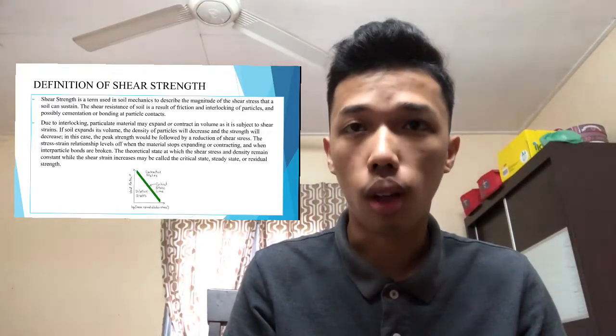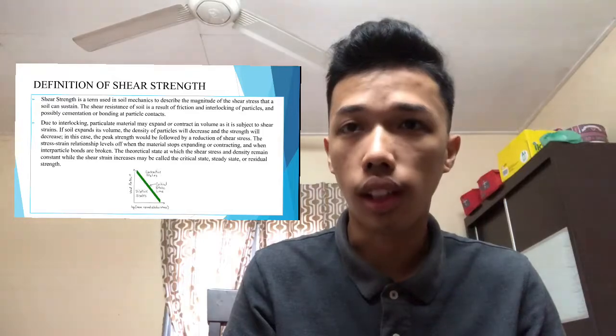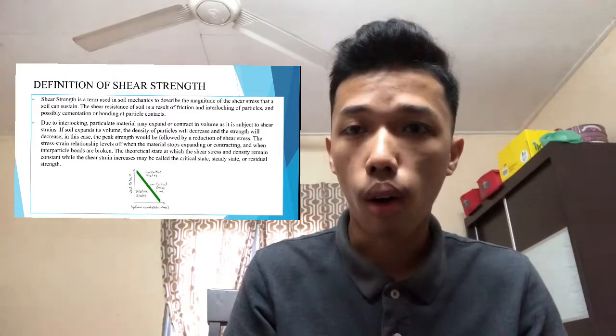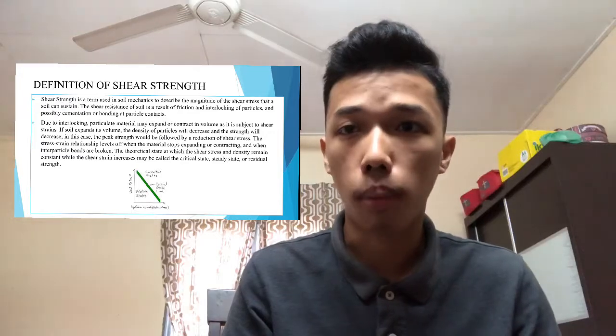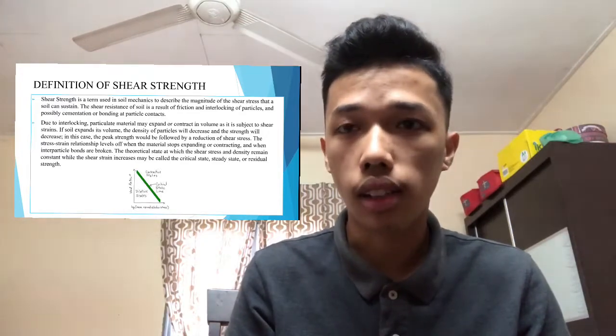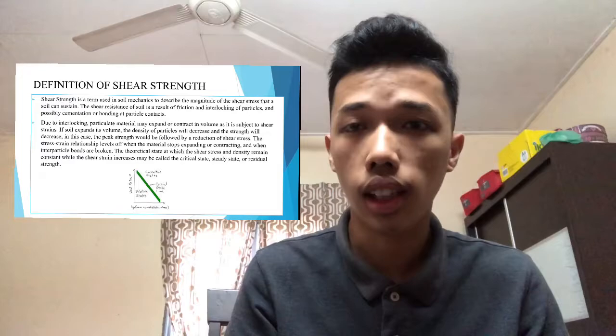Due to interlocking, particulate material may expand or contract in volume as it is subject to shear strains. If soil expands in volume, the density of particles will decrease and the strength will decrease in this case.